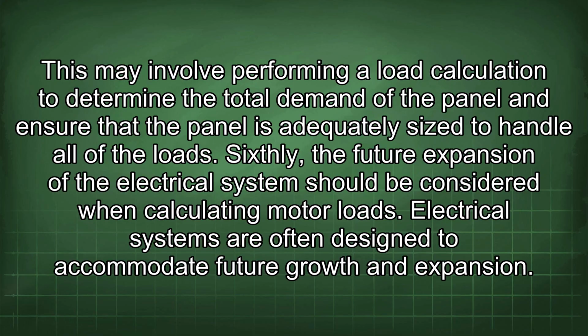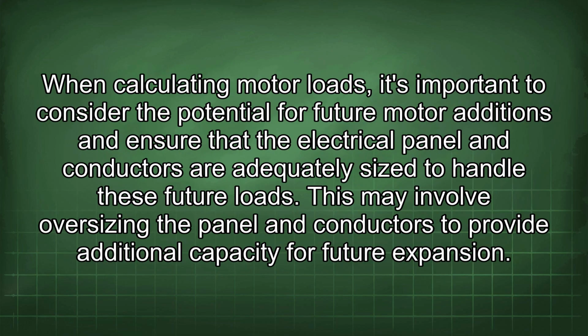Sixthly, the future expansion of the electrical system should be considered when calculating motor loads. Electrical systems are often designed to accommodate future growth and expansion. When calculating motor loads, it's important to consider the potential for future motor additions and ensure that the electrical panel and conductors are adequately sized to handle these future loads. This may involve oversizing the panel and conductors to provide additional capacity for future expansion.